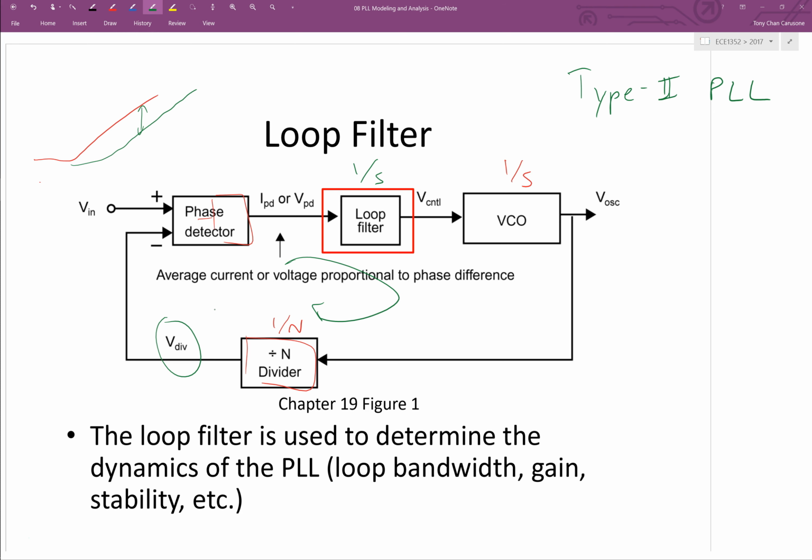Then how exactly do you do that? How do you put that integrator there? Well, we've already got, with the charge pump phase lock loop, the charge pump phase detector, a current coming out of the phase detector, right? So it's kind of obvious how you're going to integrate that and turn it into a voltage. You're just going to throw it onto a capacitor, right? So there's your integrator. I'll clean this up a bit, sorry.